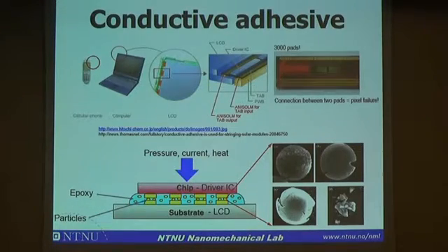But recently, the Norwegian industry has a new idea of how to use these polymer particles. By depositing a thin metal coating, usually around 100 nanometer thick, the particle becomes conductive. At the same time, it keeps the mechanical compliance of the polymer part. So we can use these particles in electronic packaging, in a component called conductive adhesive, which is the part in your mobile phone or the LCD of your PC screen.